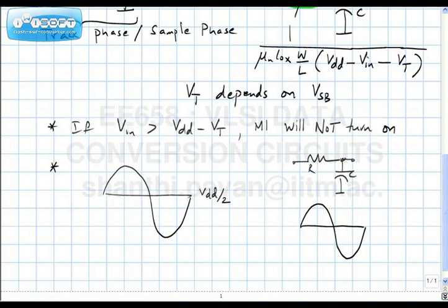The gain is approximately 1. Okay, so in other words, I am saying that the frequency of the input sinusoid is much smaller than the bandwidth. So the magnitude response is almost 1. What can you say about the phase? At DC it is 0, but the output sinusoid is lagging the input sinusoid.